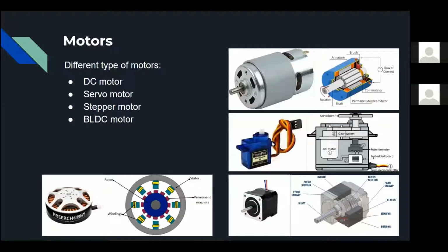So for these types of servo motors, the actual motor should be very small. If you pick a smaller motor, its speed and torque capacity will be very low. So in order to achieve the rated speed or rated torque, they introduce a gear system in between, where there will be a change in the gear ratios, which directly and indirectly affects the speed and torque of the overall motor.